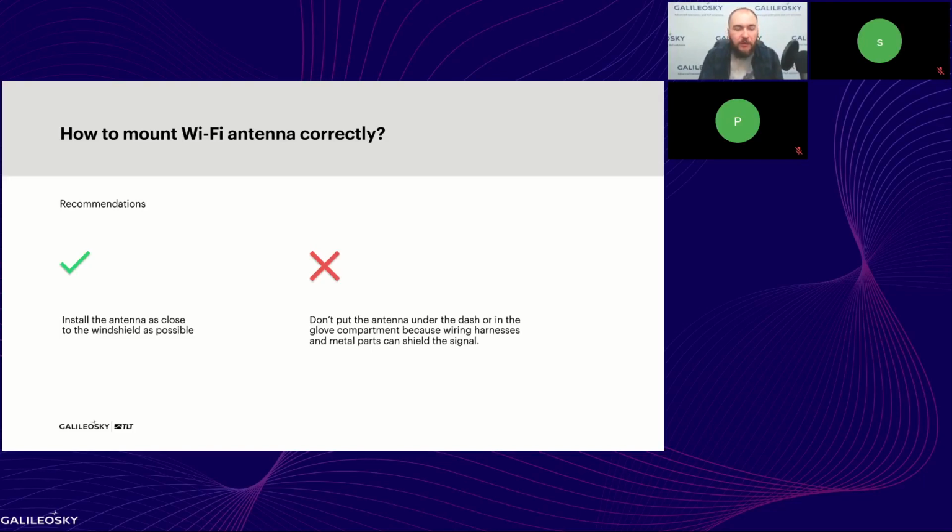According to our tests, and I was actually involved in this test, it was quite an interesting process, because in the middle of winter I was running around the office with a notebook trying to collect data from clients that were installed behind the window. Basically, we had a strong connection between the client and the hub at a distance of about 40 meters. But it was a direct view between the two antennas. You need to understand this.